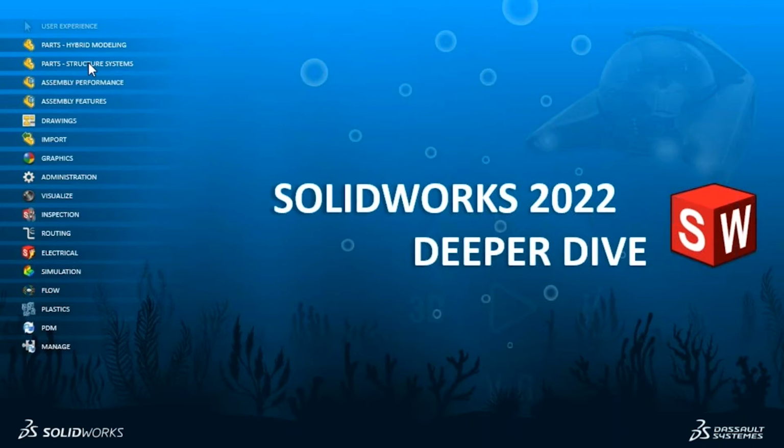It allows us to utilize data from these other packages, BREPs and things that are not solid models that we traditionally use that are done in SolidWorks, but we need them in our assembly. So hybrid modeling, because most of us are in some kind of a supply chain, right? We're either getting data from somebody and building our part to it, or we're sending parts, right? Somewhere in there, we're probably interacting with data that's not native to either your company or SolidWorks or both. And those are the cases where hybrid modeling really comes into play. So if that's you, if you're handling this data and you don't know what to do, this is a function you should be looking at.